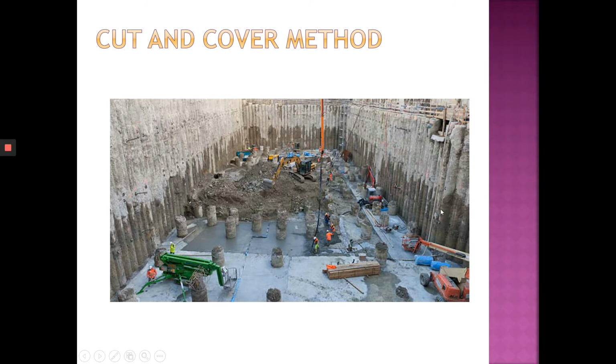So this retaining wall is actually contiguous bore pile. Bore pile biasa that you have learned in the deep foundation topic, or you will be learning about bore pile. It's the same bore pile, same technique. It's just that they do it continuously.